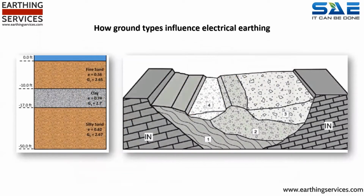Not only is a given site unlikely to have uniform material composition across its soil type, it is also likely to be subject to a number of different layers of strata. These images illustrate how the ground mass of a given area comprises different strata, each with a differing soil type. This concept of ground composition, coupled with a recognition that soil types conduct differently, convey how influential soil resistivity is on the effective distribution of electrical current passing through an electrode into that ground mass.